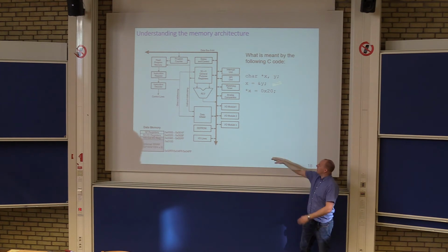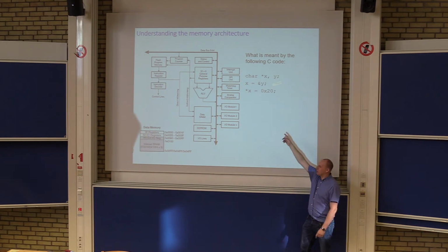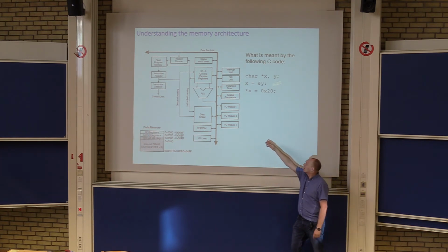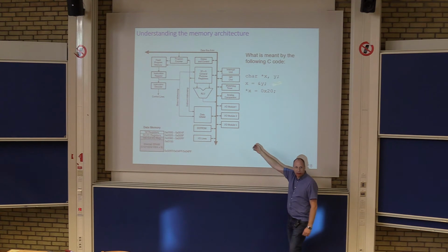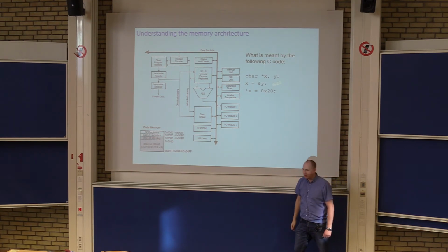And as I said, so that's one aspect, this performance aspect. The other aspect is that when you need to interact with the hardware, that's not something you do in MATLAB. To access the different I/O modules that you have, you will find them at certain addresses. So that is fixed where they are. You can go in the data sheet and read at what address we have the AD converter for the accelerometer, for example. So then you need to do these things.